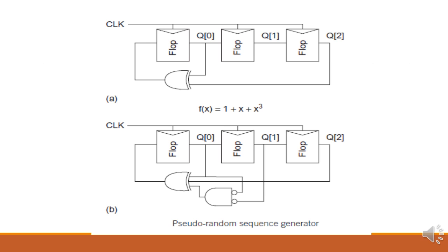So if you have a test program, then we have to verify it in a correct circuit and get the output. Then we have to compare whether that output and our output are equal or not. From this itself we can check whether it is a defective circuit or a correct circuit. So this is the structure for the pseudo random sequence generator, which is constructed using LFSR.